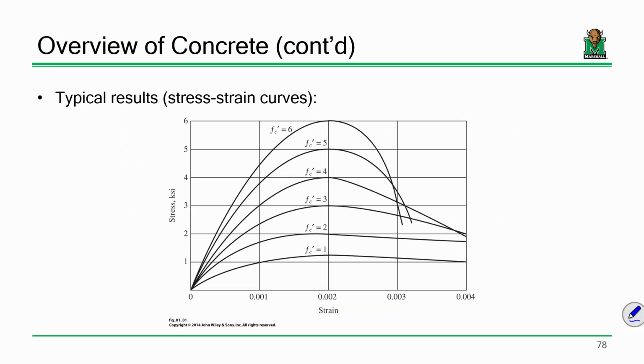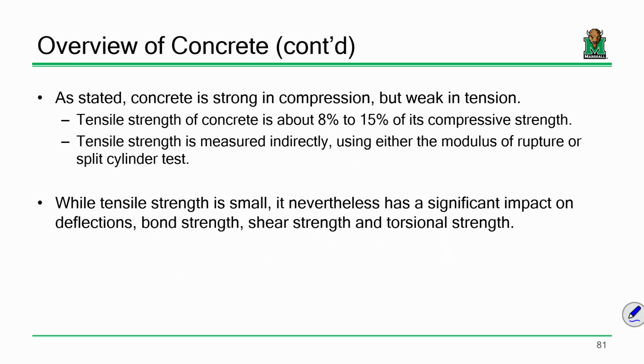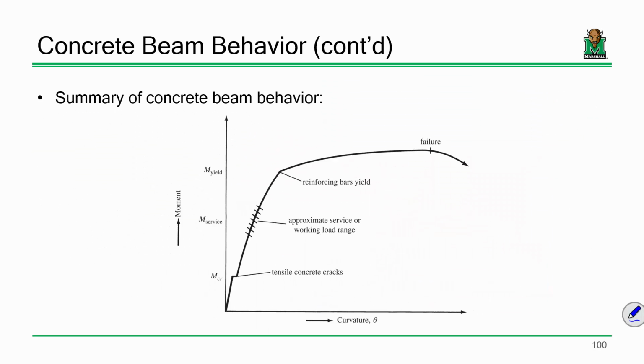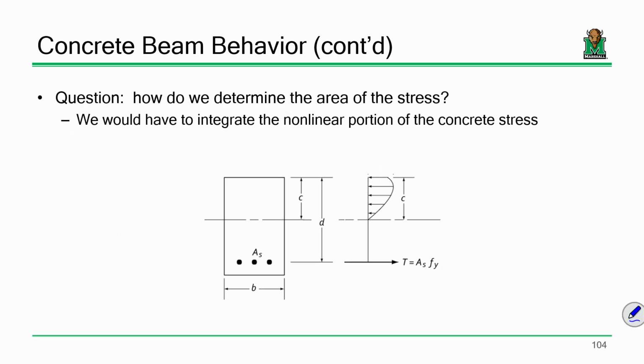This is what the stress-strain curve for concrete looks like, right? So if I'm talking about concrete behavior at its ultimate stage, isn't it feasible to assume that at the ultimate stage, the stress profile looks something like this? A highly nonlinear curve, right?